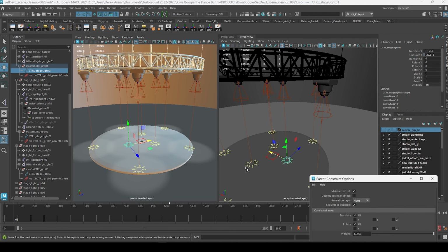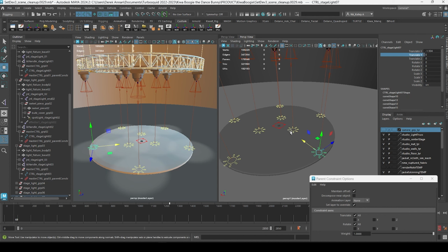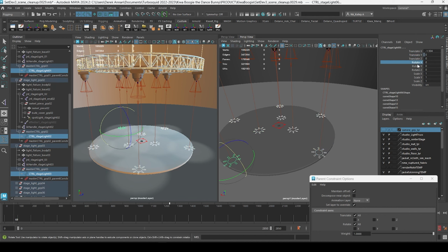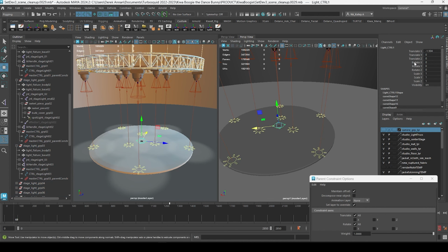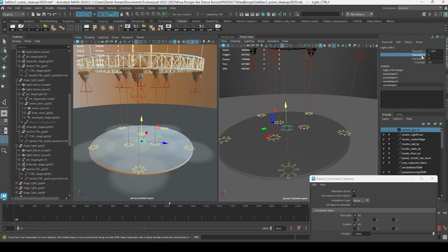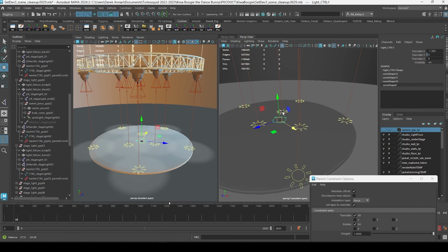And make sure I've locked all the y-axes of this controller, because the y-axes really will never have to be moved again. And I could probably do that with these two. I don't need translate y. I'm going to lock it. And I definitely don't need rotation and scale for any of them. So just to clean up the view, I'm going to lock and hide rotation and scale. I'll do the same thing for the master. I'll lock and hide selected. And lock this temporarily. Actually lock this permanently, but I might need to unlock it to make some changes. I might find that this thing is in the way and I need to move it out. So I would need access to that.